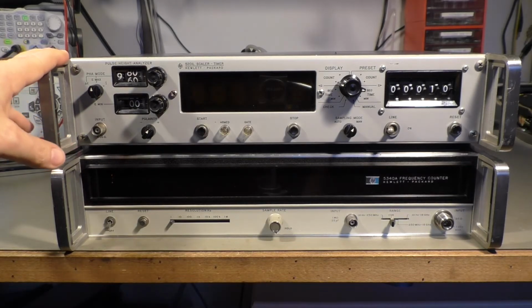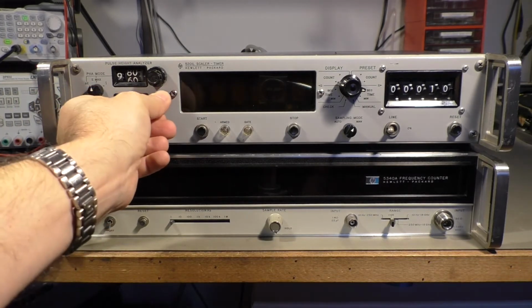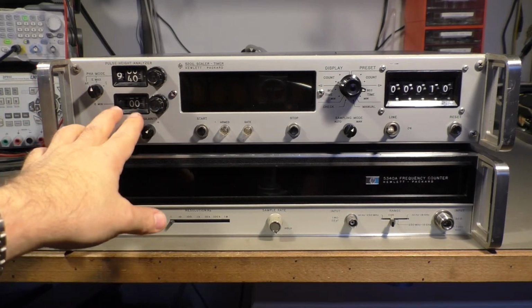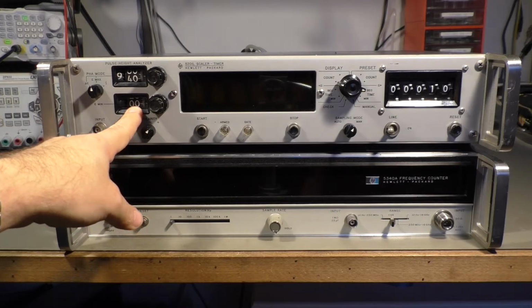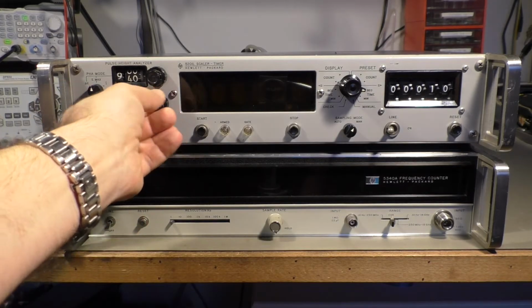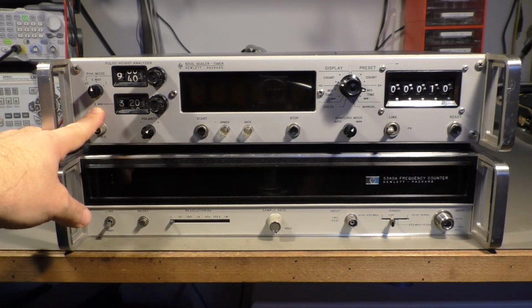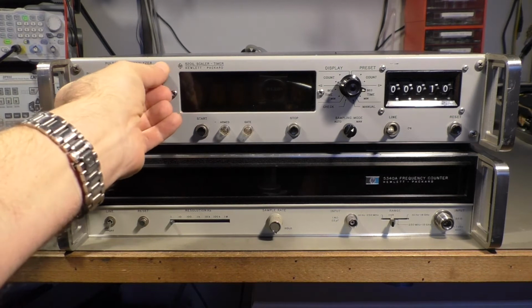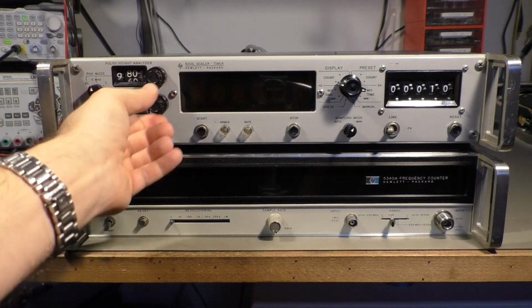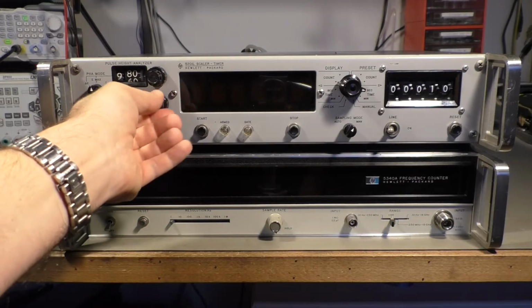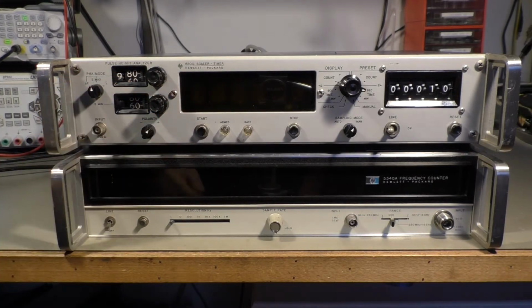The scalar part of this is here. Here you can say what is the minimum amplitude of the pulse that we want to count. We can set here an energy minimum and an energy maximum that goes to 10, and you can select the amplitude of pulses you want to count, and this gives you a clue about what radioactive source you have.